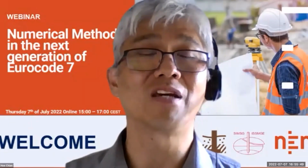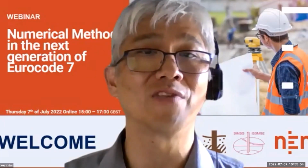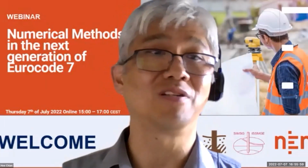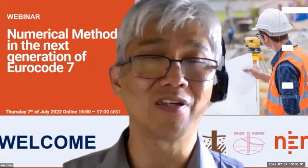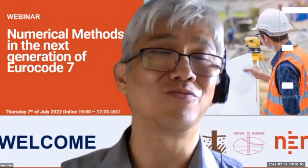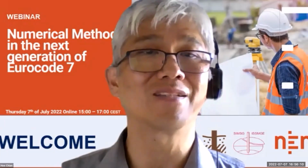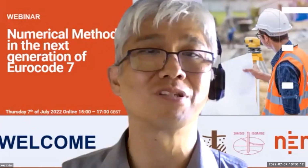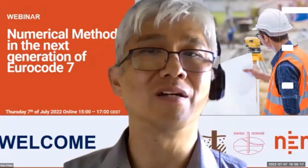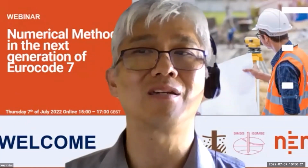But you never know. It depends on what you are building, and if you're doing something very ambitious, for example, if you excavate 15 meters with a single prop at the top, or without a prop at the top, then you might get C2 to govern because of the soil strength being fully mobilized. So it's not black and white. You need to confirm which is more critical and take it from there.